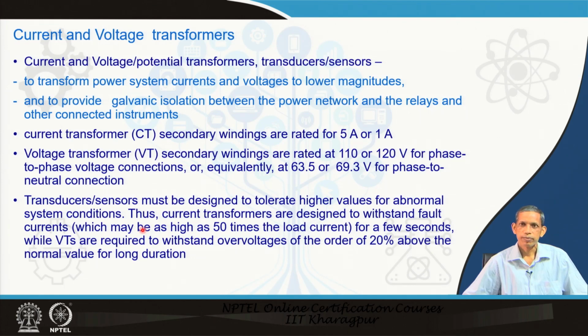In that perspective, for a current transformer, the current signal may be very large at times, and if it reaches the saturation region of the current transformer, then the information on the primary side, which will be conveyed to the relay using the secondary of the current transformer, may not be the correct value of the primary.